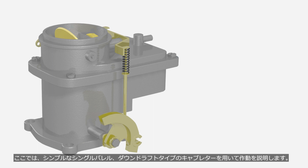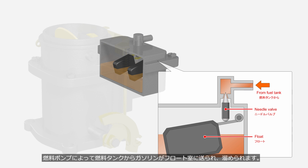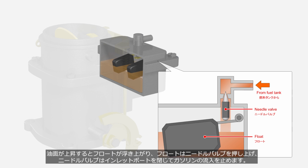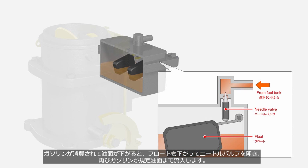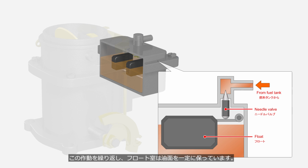Let's take a look at the operation of a simple single-barrel downdraft type carburetor. Gasoline flows into the float chamber by fuel pump from the fuel tank. The float chamber has two functions: to accumulate gasoline, and to meter the fuel level. When the fuel level rises, the float floats up and pushes up the needle valve. The needle valve closes the inlet port and stops the flow of gasoline. When gasoline is consumed and the fuel level drops, the float also lowers and opens the needle valve. Then gasoline flows in again until it reaches the specified fuel level. By repeating this operation, the float chamber maintains a constant fuel level.